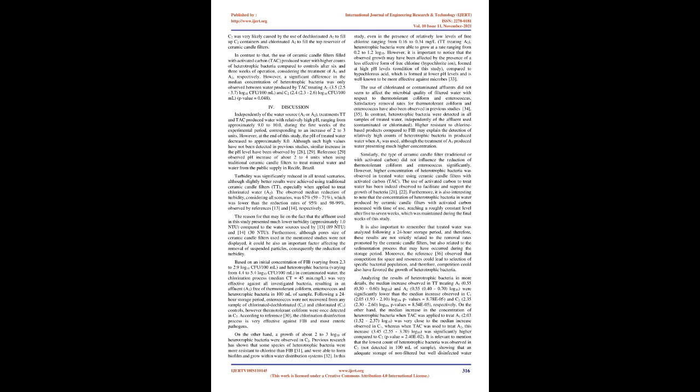Turbidity was significantly reduced in all tested scenarios, although slightly better results were achieved using traditional ceramic candle filters, TT, especially when applied to treat chlorinated water, A2. The observed median reduction of turbidity, considering all scenarios, was 67%, 59 to 71%, which was lower than the reduction rates of 95% and 98 to 99% observed by references 13 and 14, respectively.